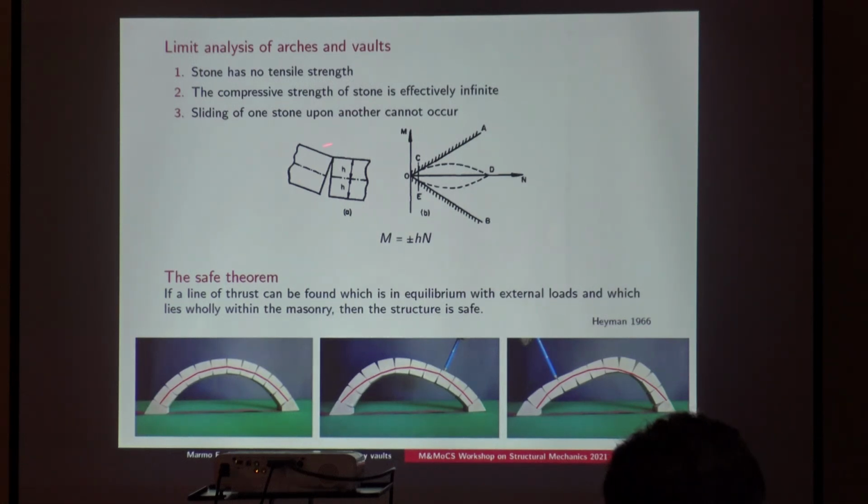But this model is just to justify that actually the behavior is ductile. That also happens in the bending behavior, even in no-tension material, which is usually ductile because you have crack openings and relative rotation. But of course, the complete behavior is ductile because of sliding. So if you are able to verify that sliding is not occurring for the distribution of stresses that you found, then it will not occur, of course.